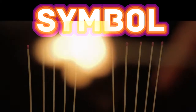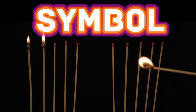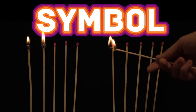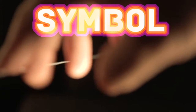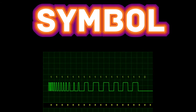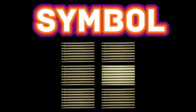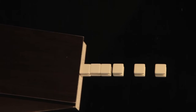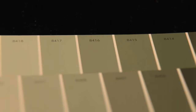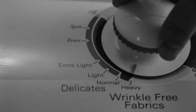Remember, a symbol can be broadly defined as the current state of some observable signal, which persists for a fixed period of time. Whether you are using fire, sound, electrical current, anything, a signaling event is simply a change from one state to another. So the symbol rate is the number of signaling events which can be squeezed together in 1 second. It also became clear that there was one other way to increase the capacity of a communication system. We can increase the number of different signaling events.